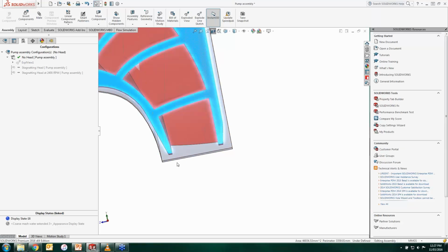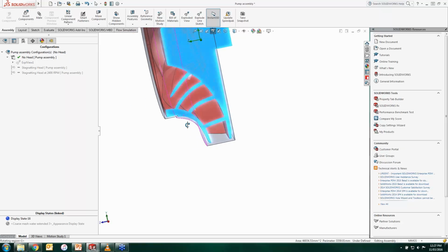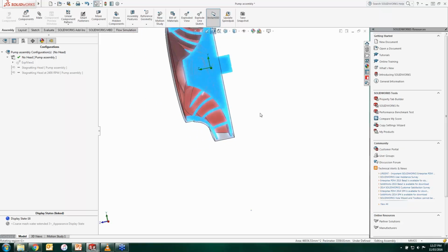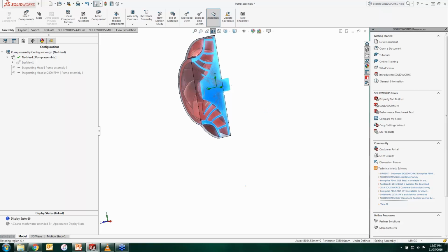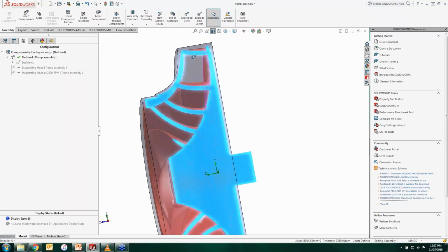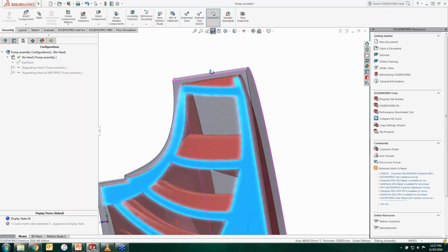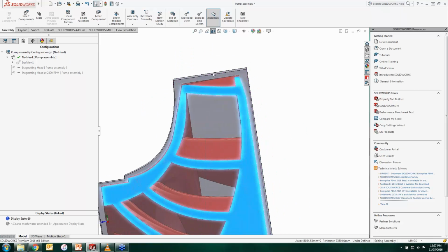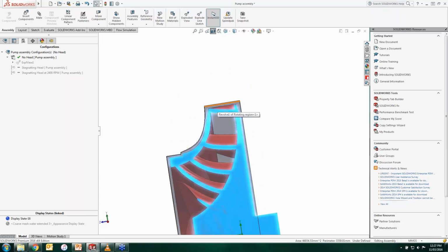Alright, around that region. What we are going to tell the software is that all the rotations are happening within that dummy face, and the rotating component inside is the impeller. It's more than important to make no crossing, keep axial alignments, and leave appropriate gaps in your design. This dummy component may interfere with any of the other solid components on the other side.